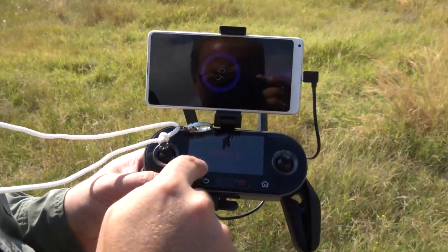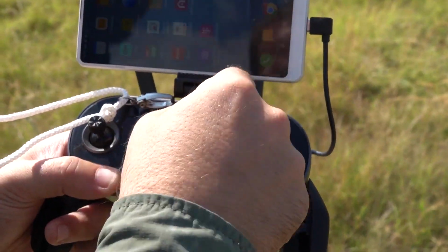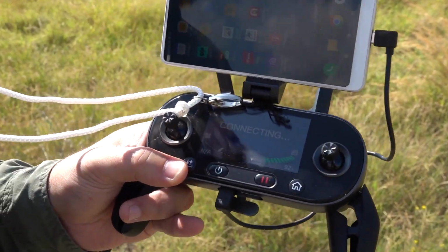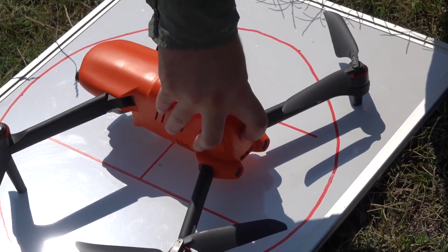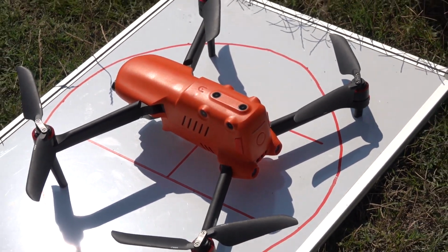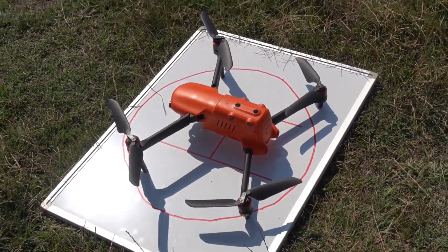After a quick check of all dependencies and locking everything tight and safe from the wind, the user can now power up the remote controller. It takes a few seconds to boot up, and when it asks for connection, please power up the drone. When these two are connected, the message "ready to go" appears on the remote controller's display.